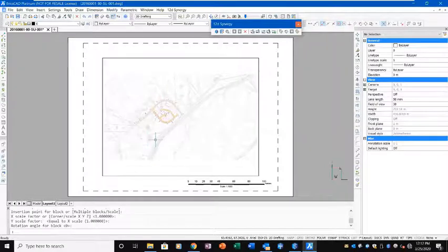Okay. When you're in a drawing, whilst you're working away on it, any saves, so your local saves here, are just saving to your workspace. You can update the server using the toolbar or ribbon or menu locations. There is an upload button there that will check your drawing in. It does leave your drawing checked out, okay? So you can keep working on it.